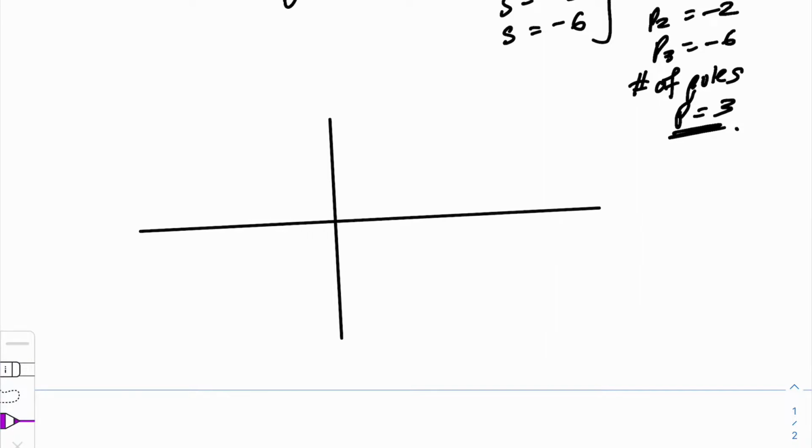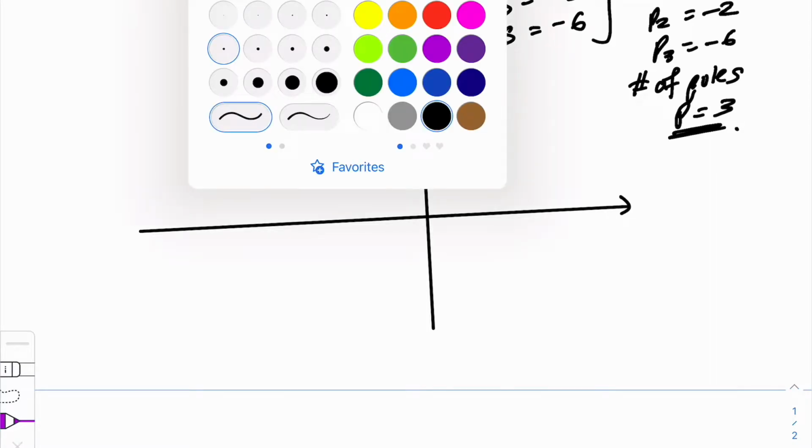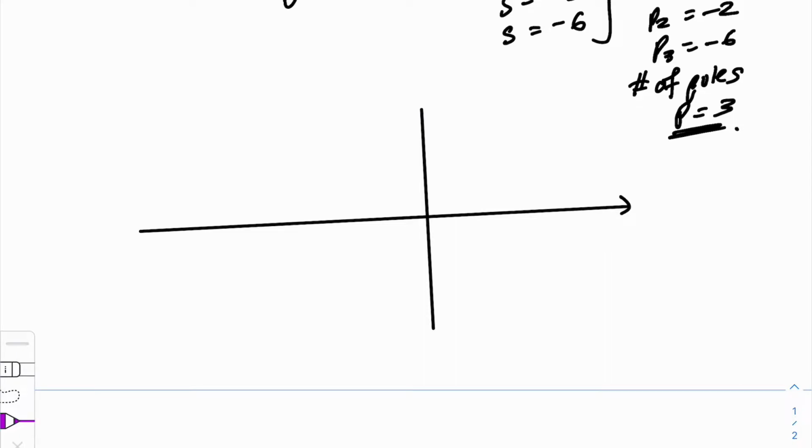Not plot but sketch. When I do the sketching, I'll just sketch nicely, but when you have completed all your steps, you actually need to plot this graph on your graph paper. Normally in an exam or test, you will be given, or you will need to provide, your own graph paper. You need to use your graph paper to plot your root locus. So you cannot just sketch. You can sketch when you're doing it, but then you need to plot it nicely on graph paper later on.